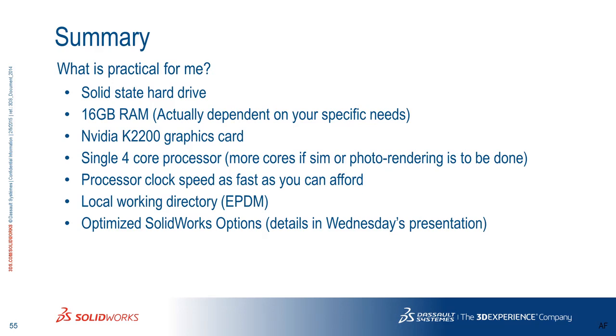And we're at the third to last slide. What's practical for you? That's what we're looking for. We're looking for the practical setup that's going to work for you, and we're talking about just using SOLIDWORKS, none of the extra stuff here. We're talking about a solid-state hard drive. 16 gig of RAM is good for almost everybody. Some people may need more, but it's rare.